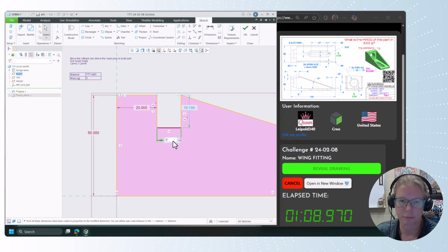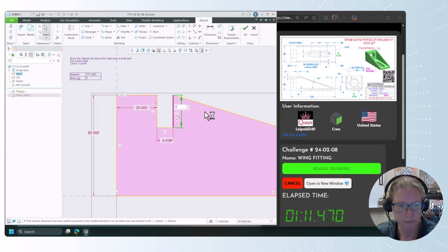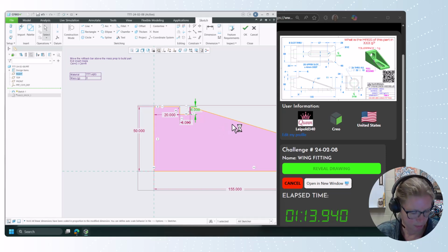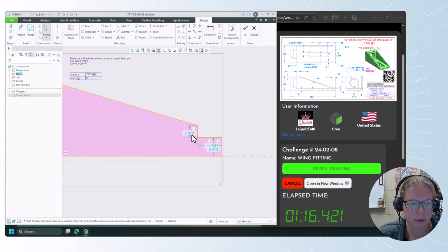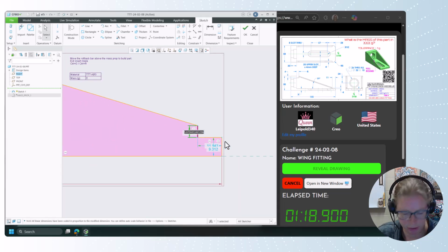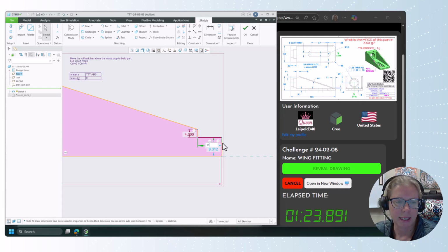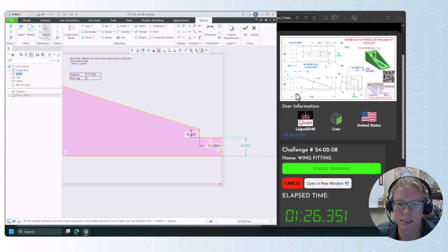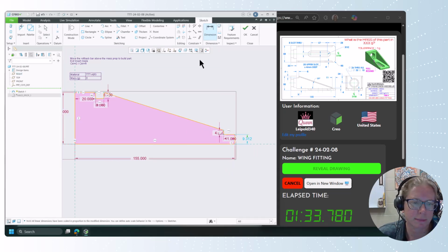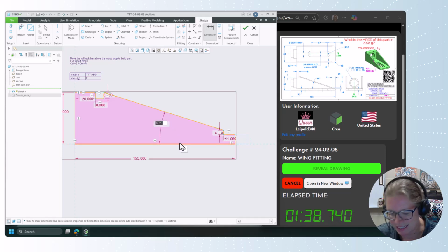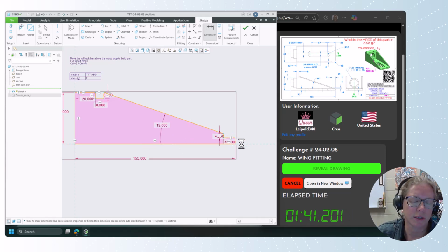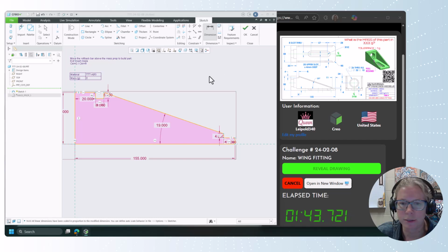This is 8. This is 6. Else this one here is 4. This one is 11. And I wish that this one was 6. It says 6 is a reference. Sometimes when these drawings are dimensioned, the reference dimension is given because that dimension is shown in another view. That's not the case here. We don't use the 6, we use the 19 degrees.